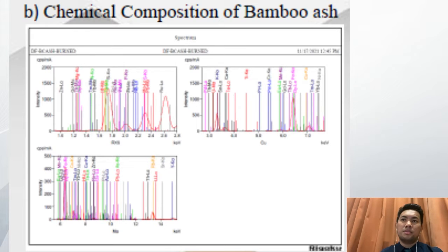As for the proportion of chemical composition, silica of bamboo ash has a value 3% greater than the Portland cement typically used in building construction material. It was tested by XRF, and this can indicate the pre-study for element detail, chemical composition, and the particle size verifies that bamboo ash has pozzolanic capabilities as a concrete replacement material for cement.